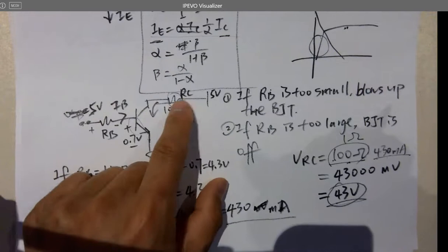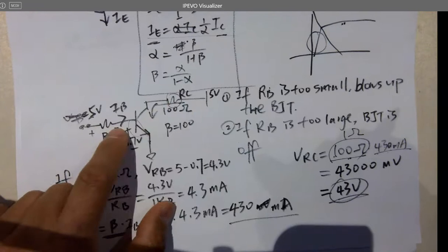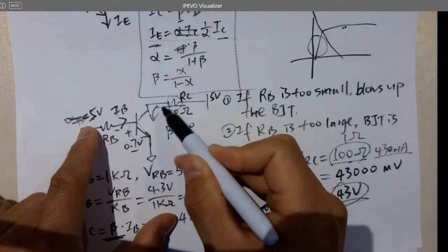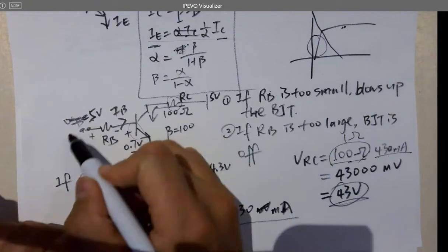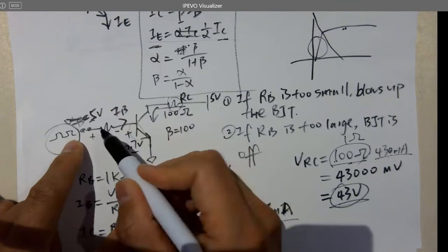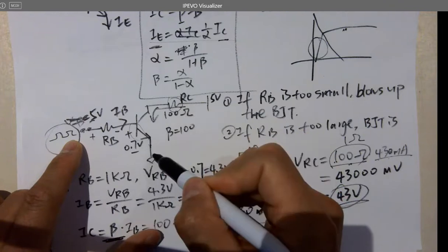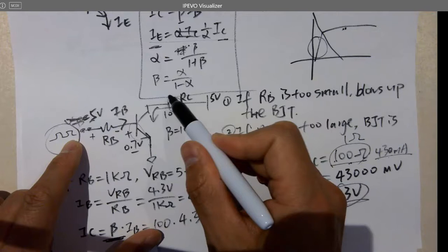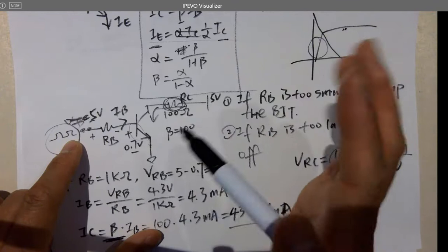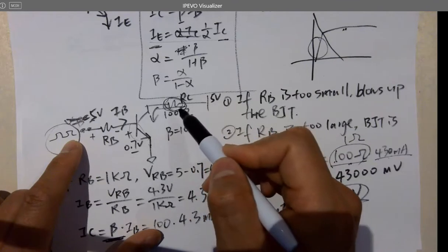So usually this can be a motor, can be an LED. You turn it on here, it draws a current from here, gets a current gain, and runs a lot more current compared to this one. That's why you can use a low current device, just running logic, just turning on and off, to turn on and off this high current branch, because usually this is a load. It can be a motor, an LED, a heater, a resistor, anything you need more current to run through.